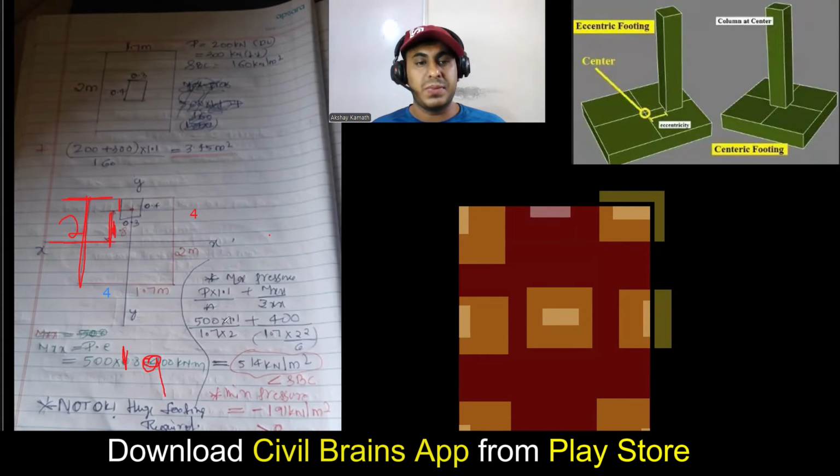Now do the calculation. You don't do it, I'll do it quickly here. P is how much? 500, that won't change, into 1.1 divided by area. Area I'm taking 4 by 4. I'm getting 34.37, I'll take 35. Then what is Mxx this time? 900 divided by, first I'll do 4 into 4 square by 6, which is 10.67. So 900 divided by 10.67, I'm getting 84.